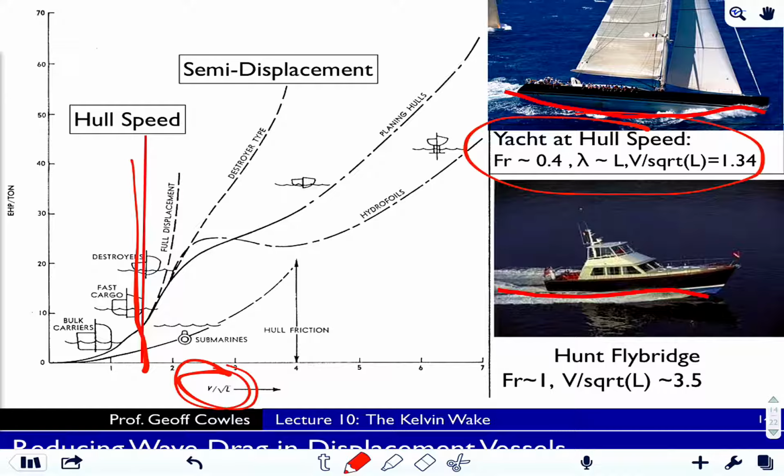So if you go to buy a displacement sailboat like this one, and you're trying to figure out what is its maximum speed, you can do that. If you know the waterline length, L, you can calculate the maximum speed, because 1.34 is going to be your maximum speed to length ratio, roughly, and this gives you your V in knots.